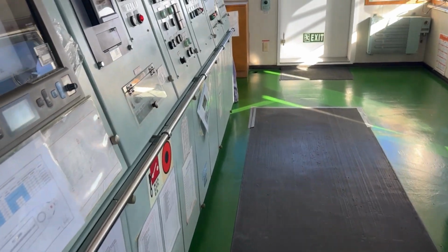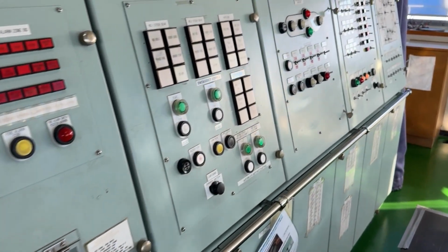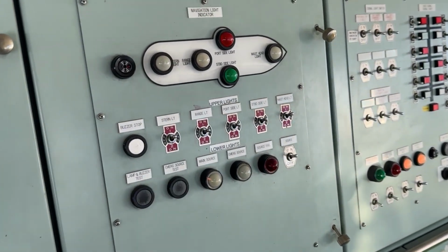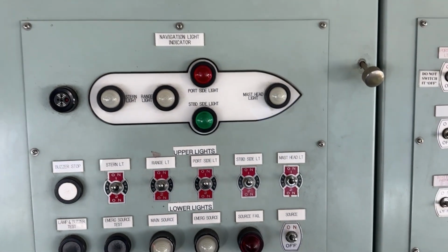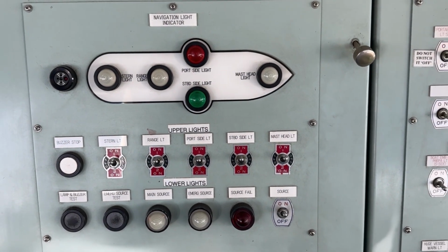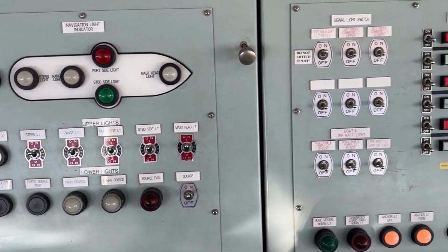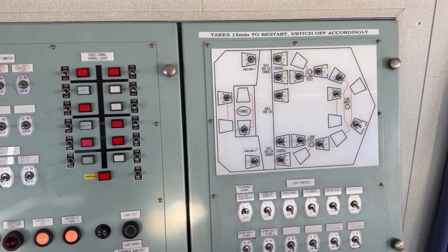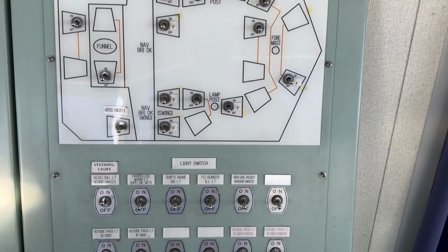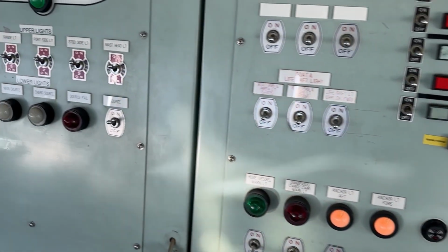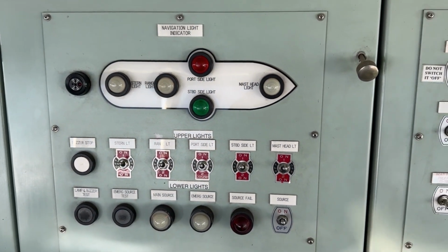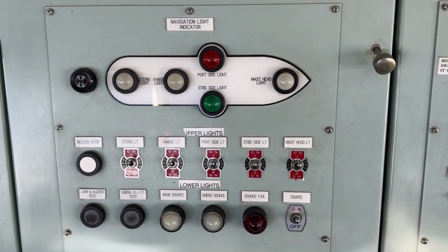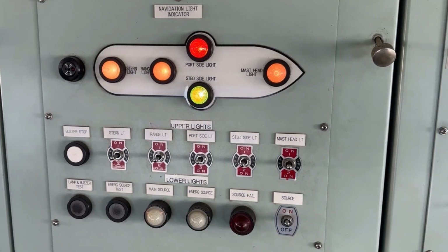But today I got low insulation when we were departing from the port. Before departure, the bridge checks several safeties as per the pre-departure checklist. In that checklist, one of the checks is to check the navigational lights. So I asked the bridge whether they had switched on the navigation lights. This is one of the simple tricks to locate the low insulation.